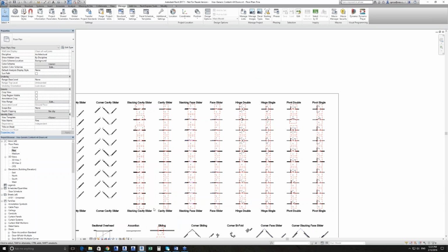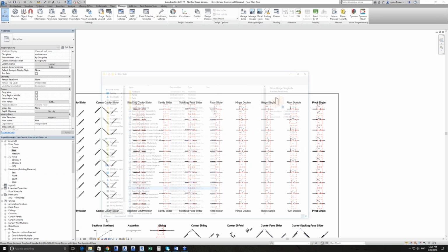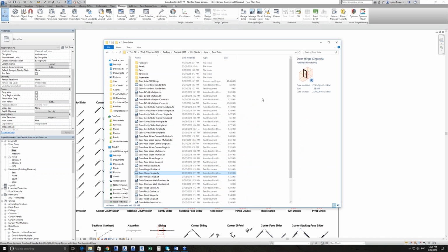Kiwis, sorry, we've got a few Kiwis in on the webinar as well, and they're asking about the different door sizes. They use an 810 door instead of an 820 door, for example. We haven't included those particular size options in our type catalogs ourselves, but it's very, very simple to open up that file in Excel and do a swap and replace of all 820s and change them to 810s. So that's not difficult, and as we get more New Zealand people on board, we'd be happy to create a New Zealand specific type catalogue, just as we'd be looking to do a US or a UK specific type catalogue. Yep. Cool.